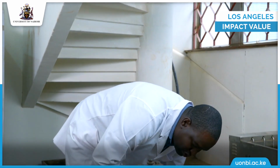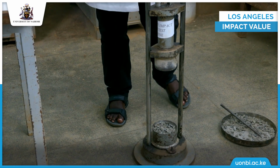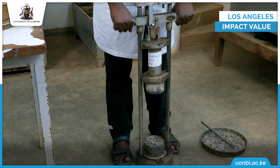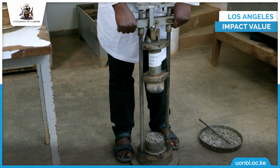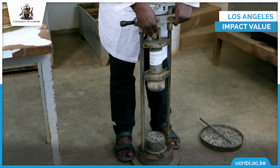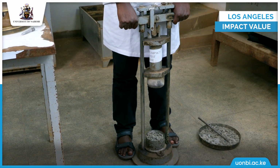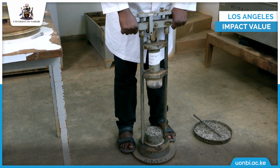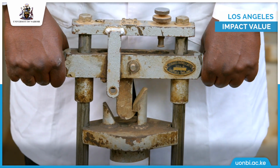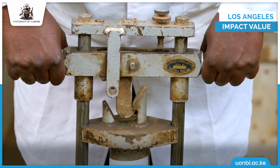So we are expected to anchor it at the base and raise the hammer a little bit using the handle to remove the safety pin. Once you remove the safety pin, if you raise it further higher, the hammer will fall into the sample. So we are going to do 15 blows. And just like I had explained earlier, you do it in a span of 1 second. So we are doing 15 blows.